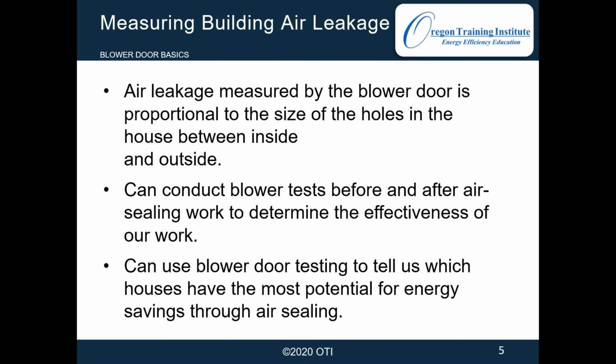And we can use this to benchmark before and after, to give the crews the idea of how much air infiltration they're looking for, the size of the holes. And then we can combine the blower door with other techniques to more thoroughly evaluate how well connected the attic or the crawl space is.